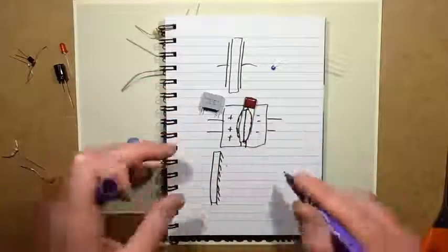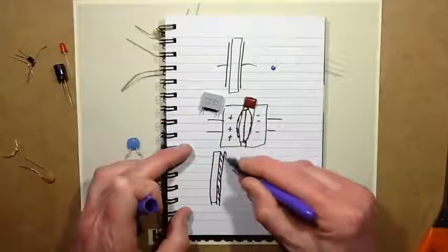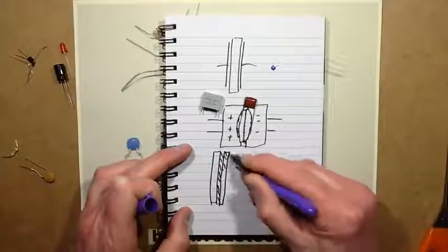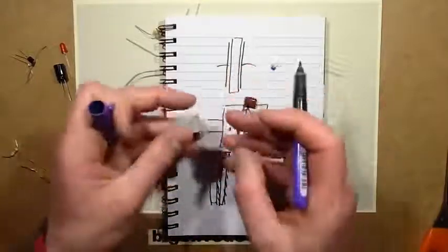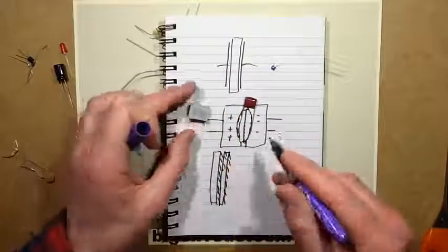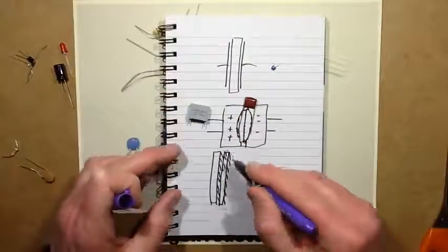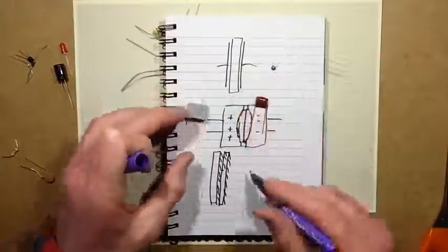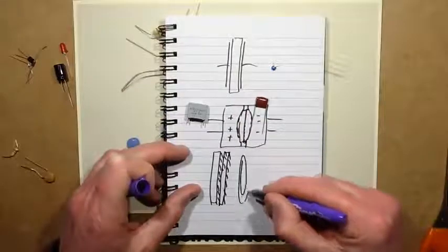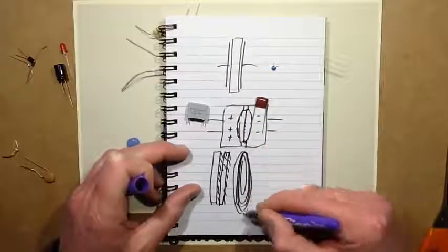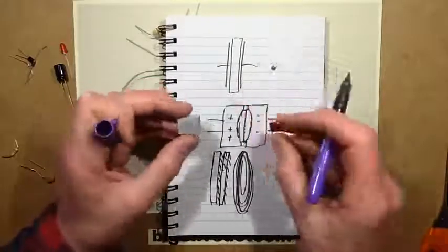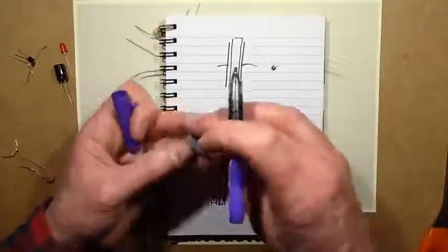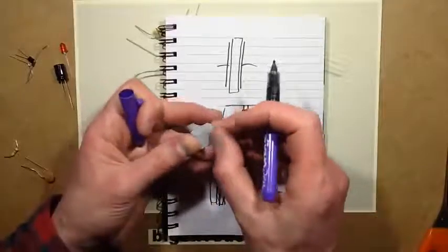And they take two strips of it and sandwich them together. The plastic is the insulator, and the metallization is the electrode. To fit a lot in a small area, they then spiral it. They take a big long strip and spiral it round into a small area, and that's what creates the larger area. And the thickness of the plastic film itself will determine the voltage rating.